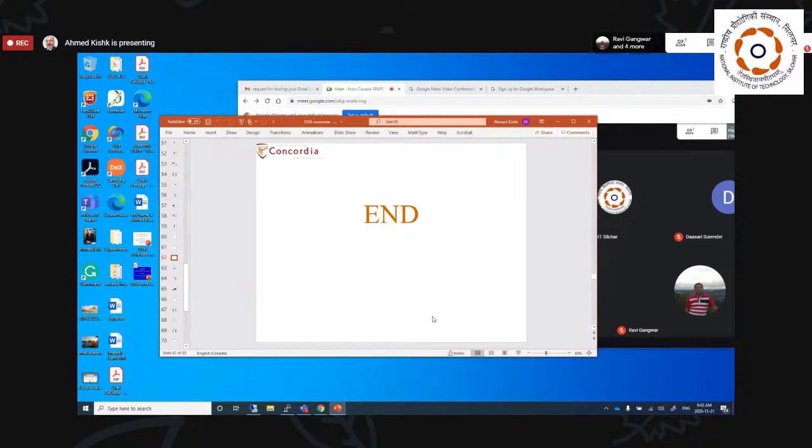No, you see, in the rectangular DRA, the TE and the TM are equivalent to hybrid modes in the cylindrical structure. The only reason we relate to TE and TM is that when people analyze it, they analyze it based on surrounding side walls of magnetic conductor, and they deal with it as if it is a piece of dielectric inside a magnetic wall waveguide.